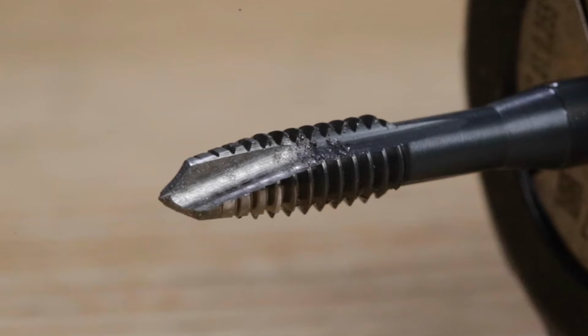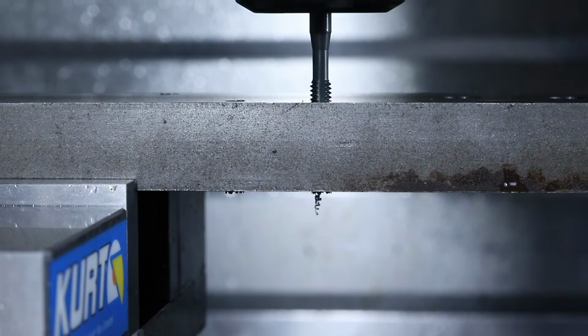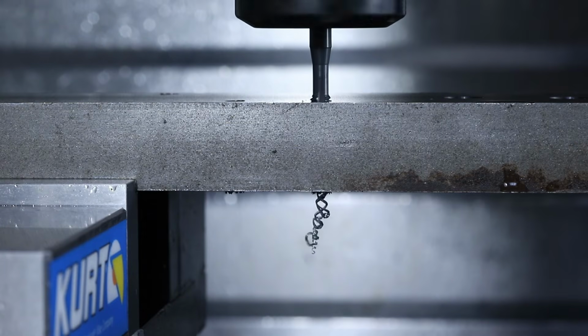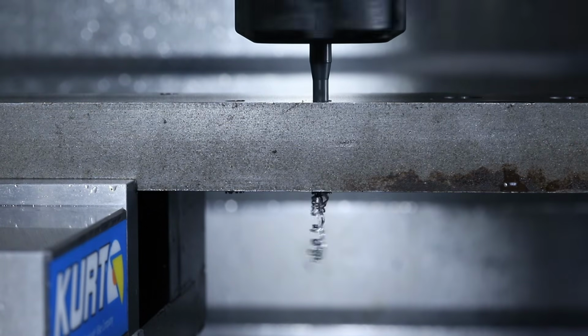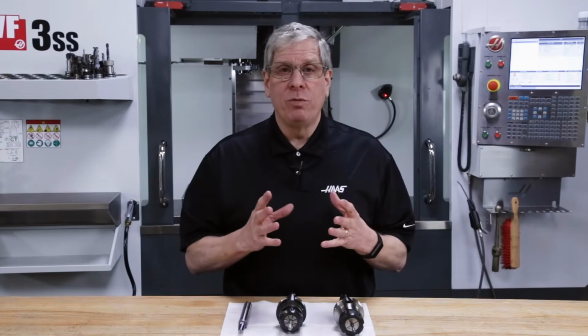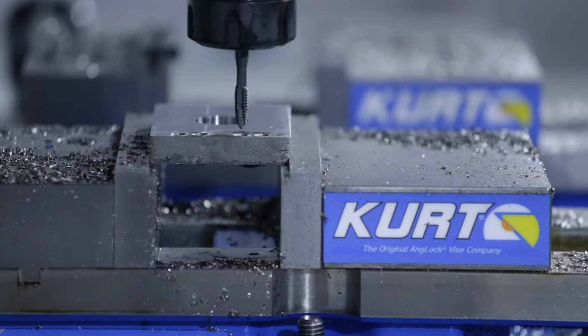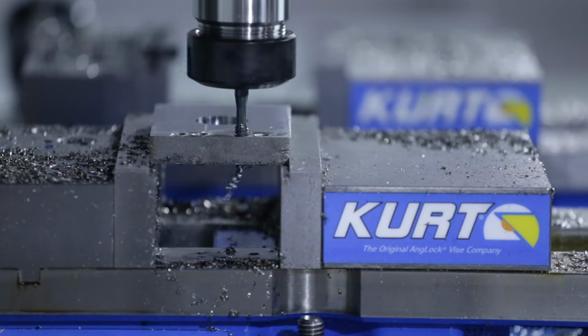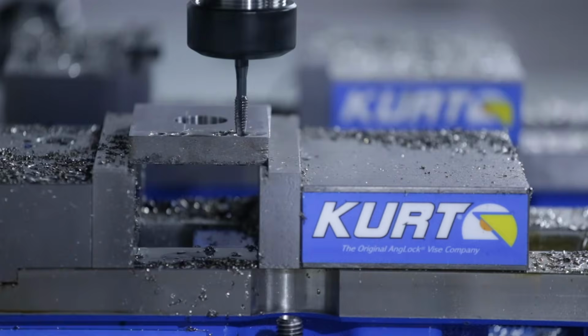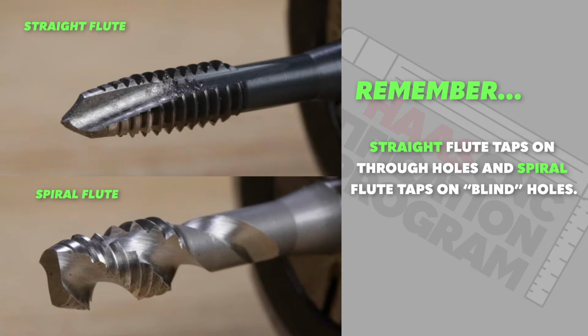Taps with straight flutes push chips down into the hole. These work great when the hole goes all the way through the material so the chips can come out at the bottom of the hole. If the hole does not go through, you must drill really deep. If you don't leave enough extra room for the chips, you'll break the tap every time. Here's the general rule of thumb. Use straight flute taps on through holes and spiral flute taps on blind holes.